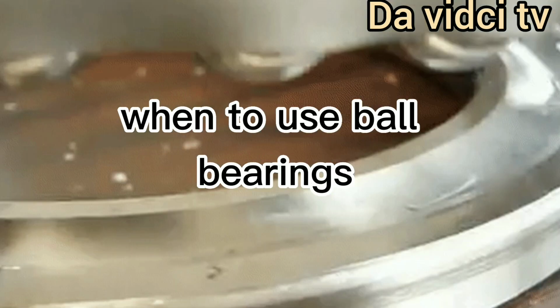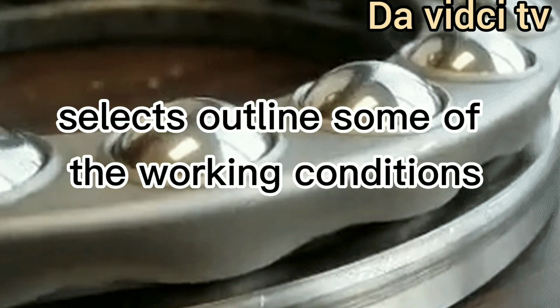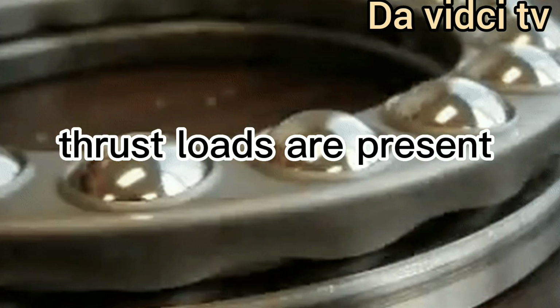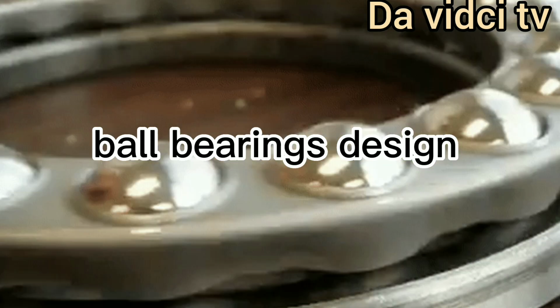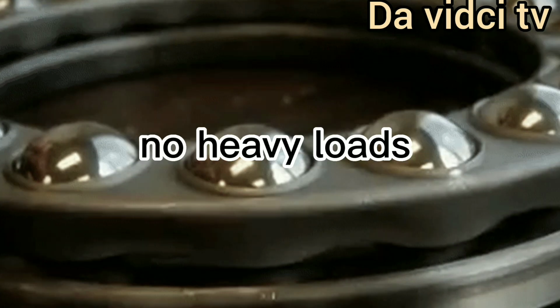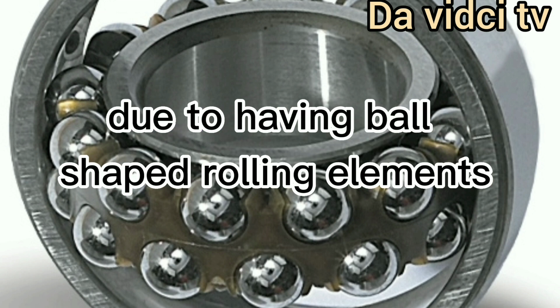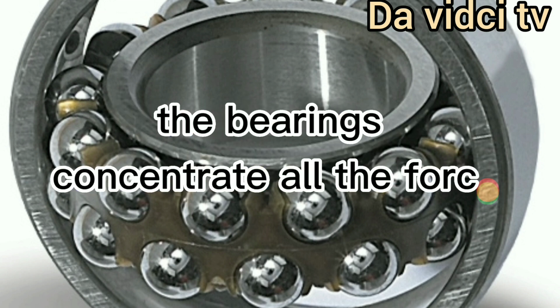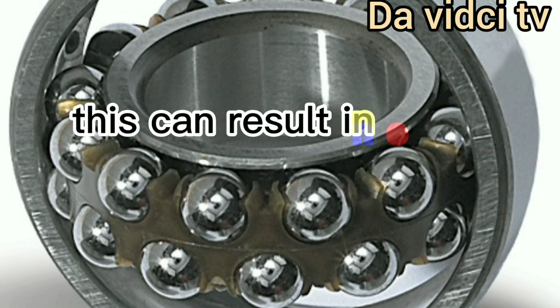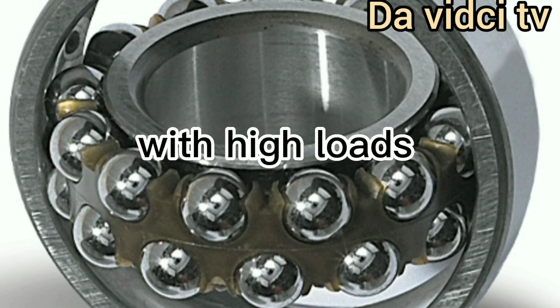When to use ball bearings. So let's outline some of the working conditions that may require a ball bearing. Thrust loads are present. Ball bearings' design makes them capable of withstanding axial loads. No heavy loads. Due to having ball-shaped rolling elements, the bearings concentrate all the force onto a few points of contact. This can result in early failure with high loads.